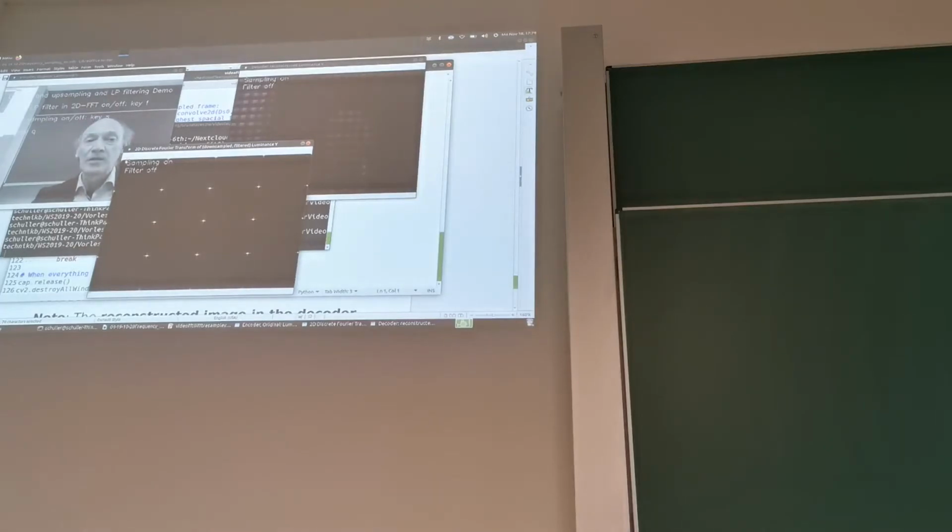So basically this is copied in between and also vertically. Right. So here we can see we get 3 copies, or altogether 1, 2, 3, 4 versions of our components. So this happens when we do sampling. We get multiple copies of the original spectrum.